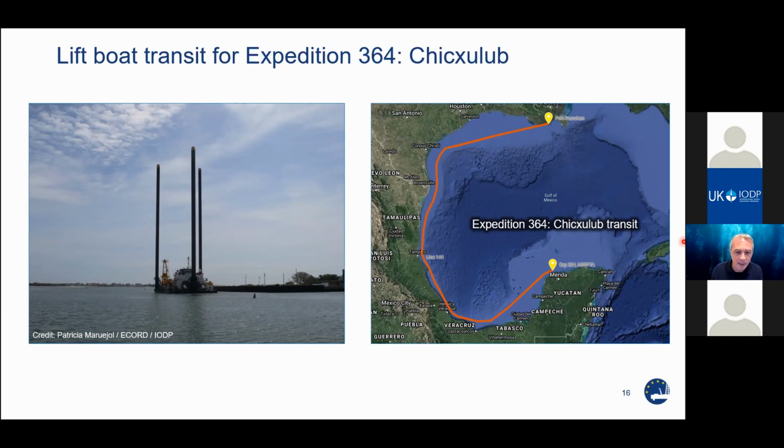So these lift boats are best for expeditions in certain locations near lift boat markets and with sites that are in a narrow water depth range. If the site water depth range has to be wider than the capabilities of a lift boat, then you need to move to a geotechnical vessel.